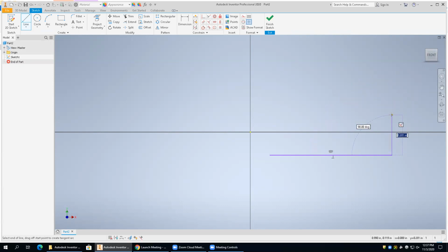So I just want you to bring this up again. Don't worry about the distance. Click a point. Do another one that's going to be perpendicular. Do another one, perpendicular. And we're going to come over perpendicular. And if you get it just right, you'll notice that little dashed line that kicks out there. That's showing me I'm opposite my starting point. That's what I want to be. When I see that, click, and then we're ultimately going to close this just like that. So we just generated this general L-shaped tool.